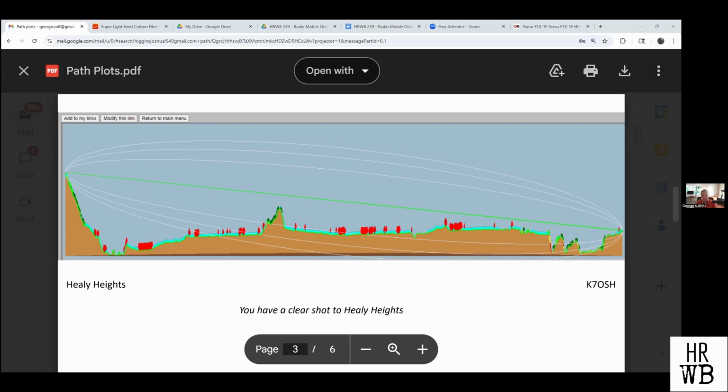Anything below 5 microvolt is lost into the noise. You say, but this is not right because my receiver has a 0.25 microvolt sensitivity. That's not the case. The threshold is not the bench test. The threshold is what you get in the field. And you have to take into account the noise, which is the main limiting factor. I didn't mean to interrupt you. Go ahead. So in VHF, you will probably have to put your threshold to more than 1 microvolt.